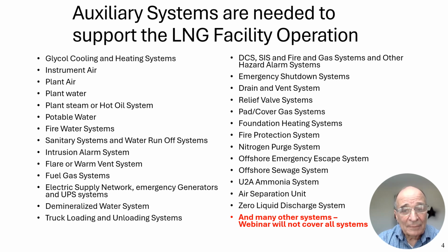Foundation heating system is needed if you have a large LNG tank that is placed on the ground. If it's on the ground, it'll be sucking heat out of the ground, and when it does that, the ground could freeze up and heave up and damage the tank. So you need to heat the foundation, and foundation heating systems are critically important.